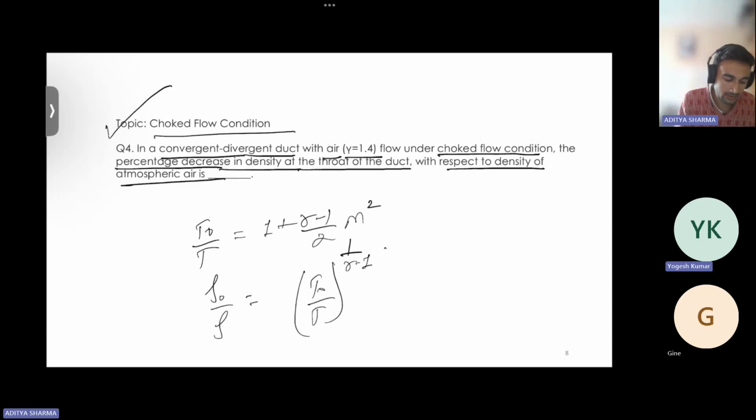So this is the static pressure, all right. In any case, if you want the pressure at this throat, that will be static pressure, all right. Because stagnation pressure and total pressure, if we consider isentropic conditions and no loss of total pressure, they both are one and the same thing.